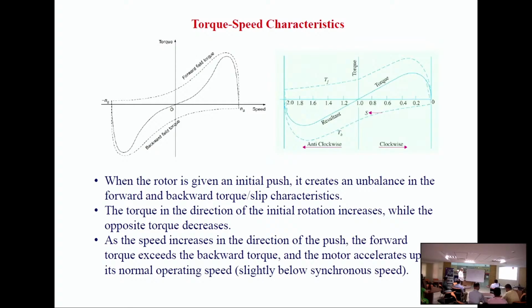So if in any direction we give an initial push, in that direction the torque will continue to increase and in the other direction the torque will continue to decrease, and finally it will settle at an operating point depending on the load on the motor.